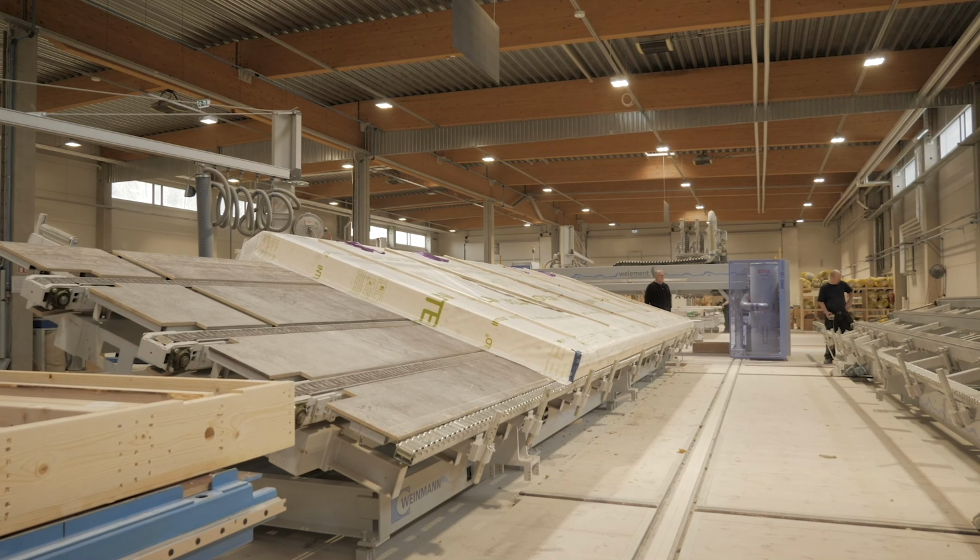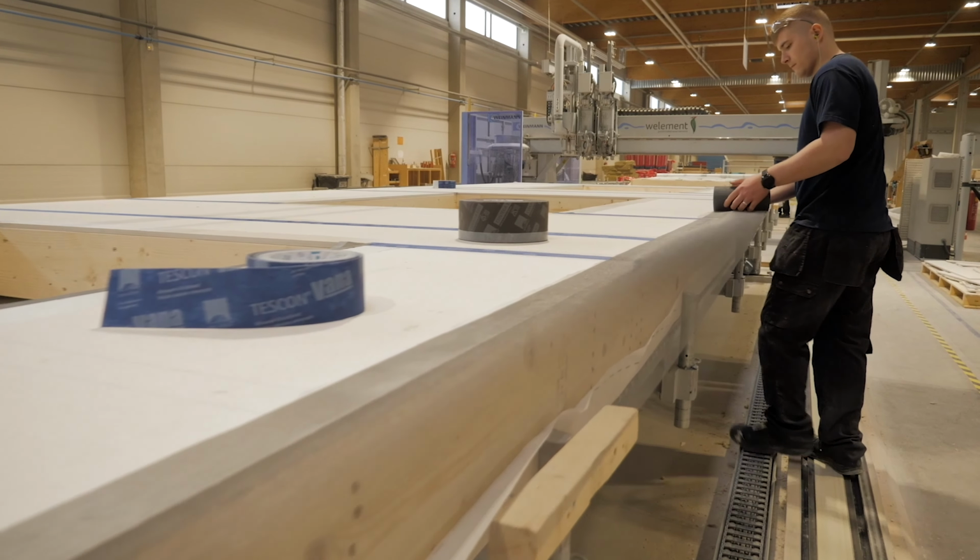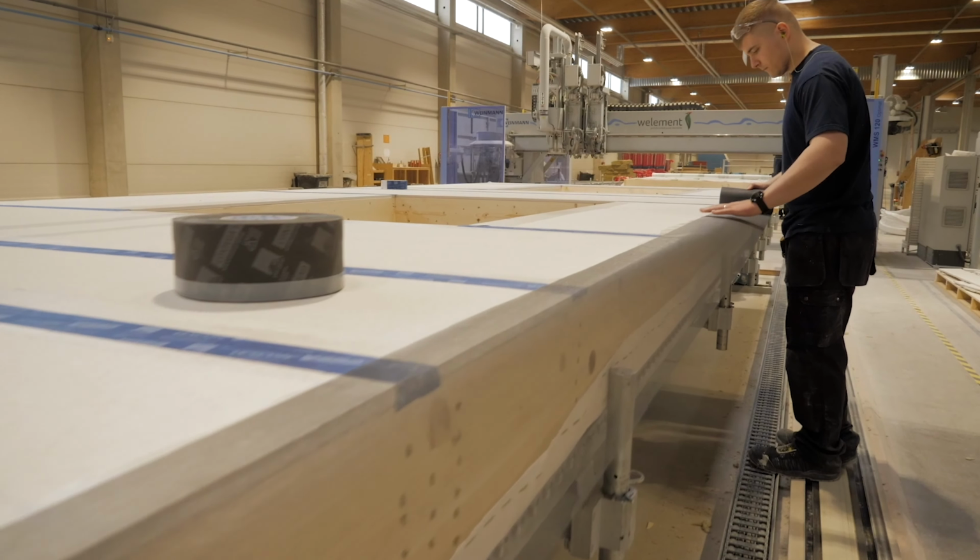Carefully attach the wind barrier panels to the frame, ensuring they are aligned and maintaining consistent gaps between them. Regularly check the alignment while securing the panels and cut off any excess material. Next, apply an adhesion improver to the gaps between the panels and around the open edges. This will help secure the sealing tape and insect net tightly.